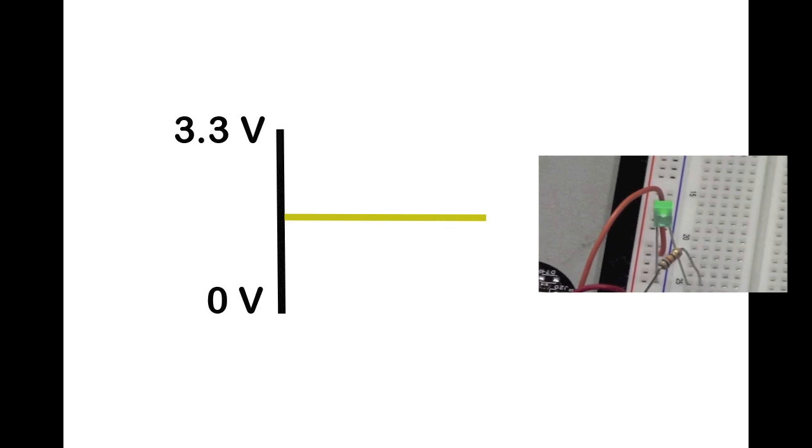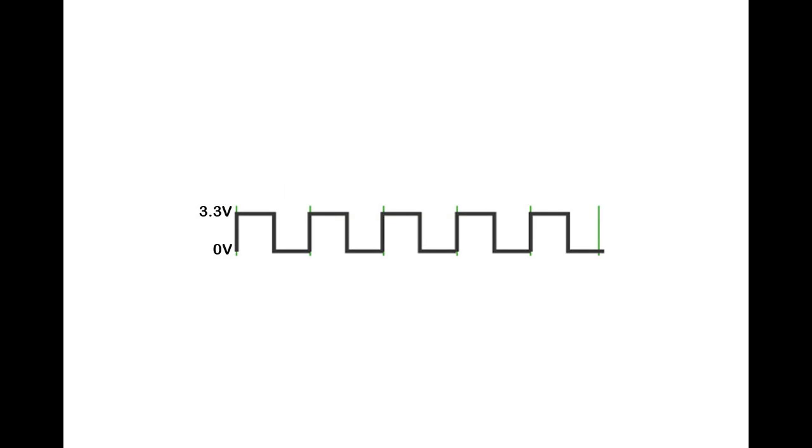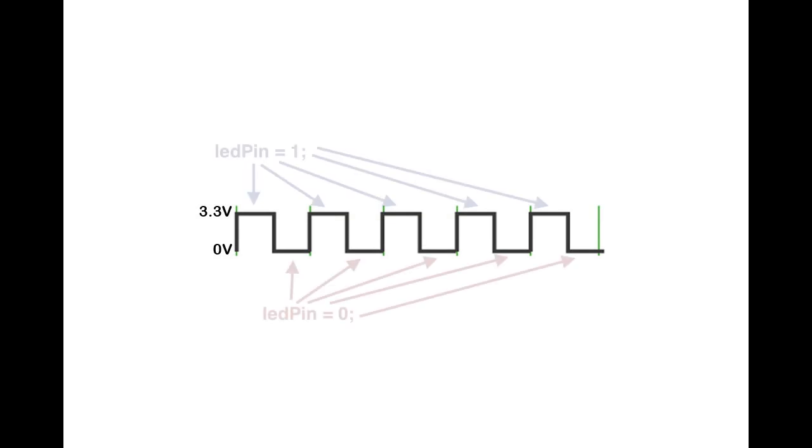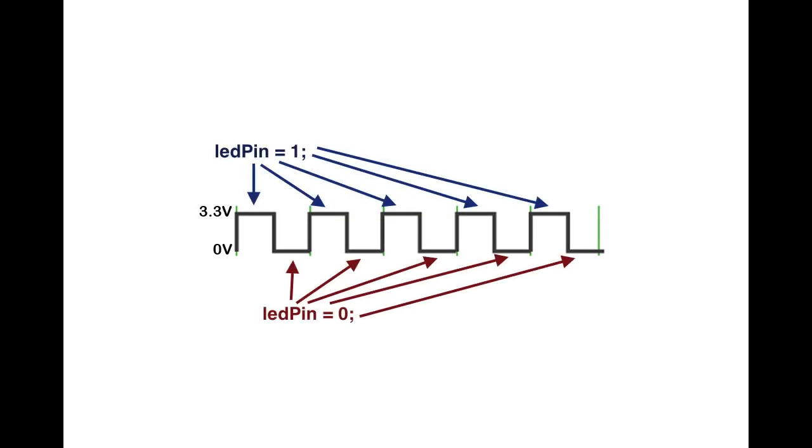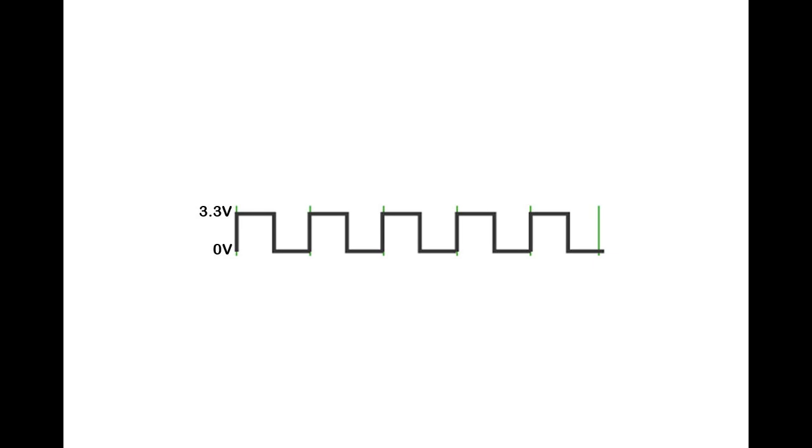Also note that this method works great for anything that cannot respond fast enough to pick up the quick flickering, like motors, since they take time to accelerate and decelerate. Really, you could just quickly write some code that turns on and off an LED really fast, but there's another method you can do instead. This method is called pulse width modulation, or PWM for short.